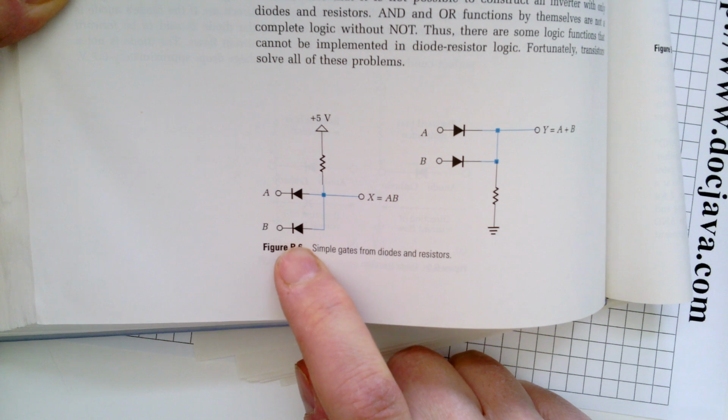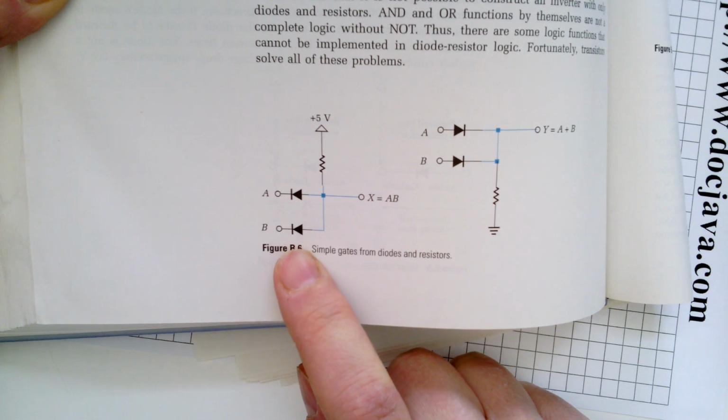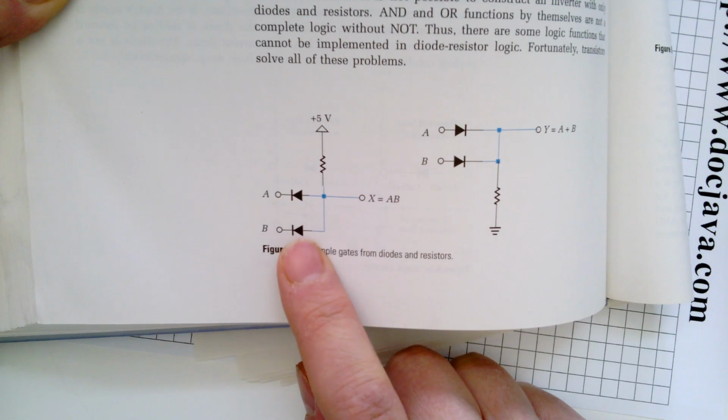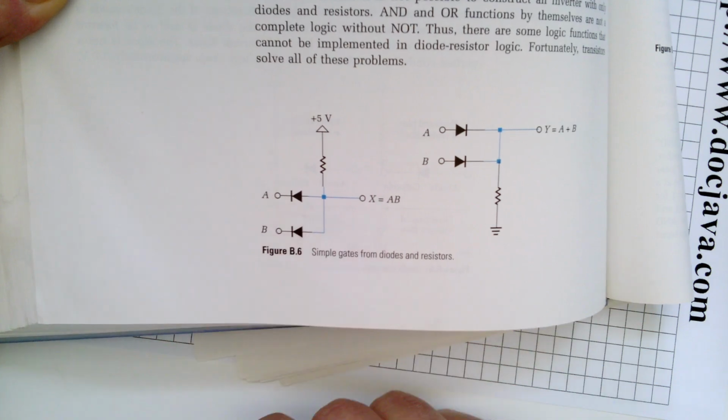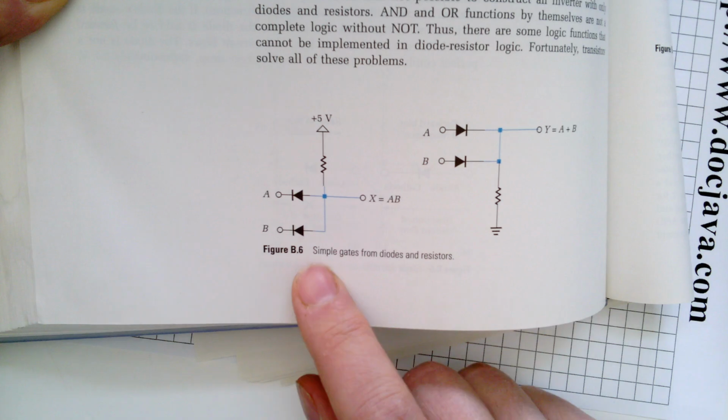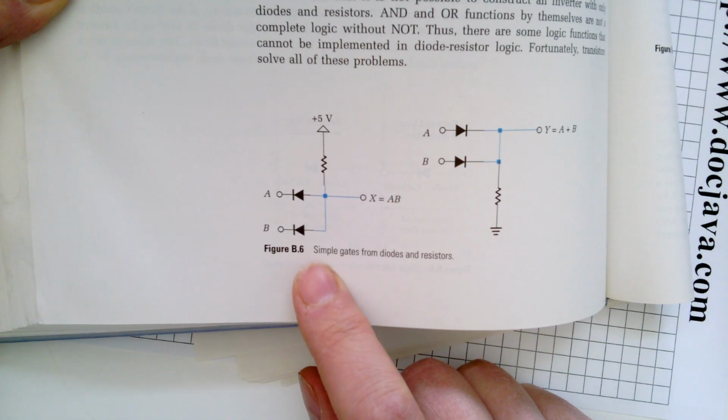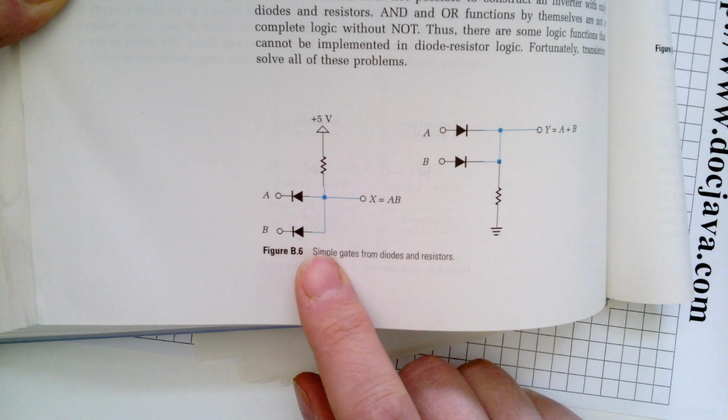And in fact, you can have what the diode transistor logic, or DTL, is needed because the transistors amplify since the diodes drop voltage. So after the diode has dropped the voltage, you go into a transistor and you pump the voltage back up again. And that was the principle behind all the diode transistor logic which existed so many years ago. Nobody uses it anymore, but that's the old style logic.